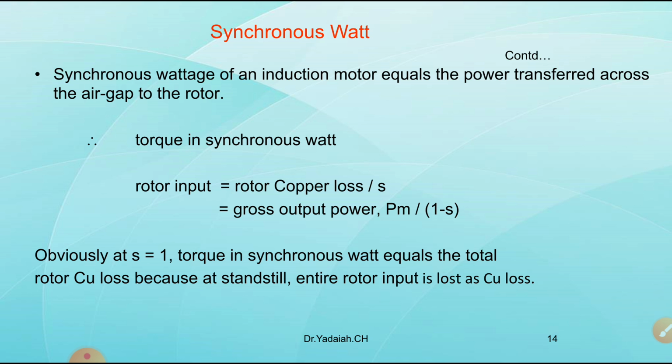Dear students, you can observe this sometimes when we switch on the supply for the ceiling fan in our home. If the condenser fails, what will happen? If you switch it on, it will give some humming sound, but it will not rotate. After a few seconds or one or two minutes, switch off the supply and you observe the heat evaporated in the fan. The heat may be very high. If it continues for that time, what will happen? The winding will fail, the winding will burn out. How is the heat generated? As per our copper losses.